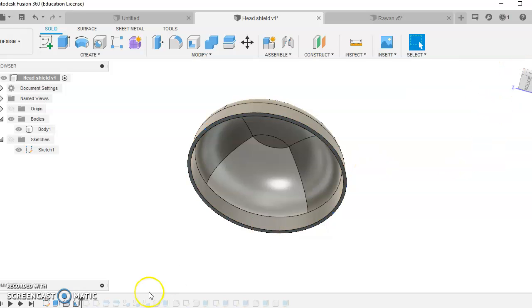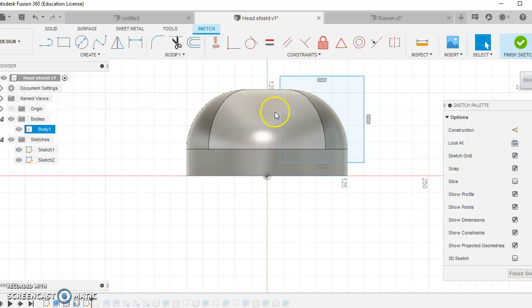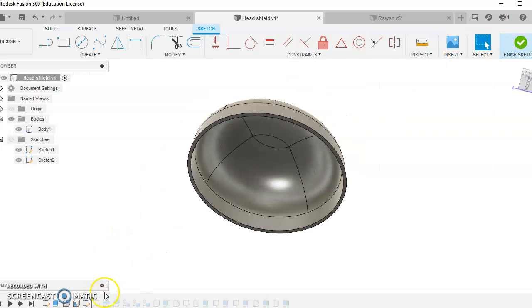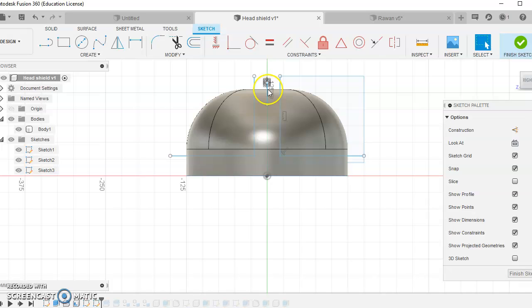Okay, so once you've got the shell done, you then go to the next stage. Now here, if I go to Edit Sketch, you can see I've created a rectangular shape. I've got a center line next to it. I mirror about that center line. Okay. You'll see on the next sketch here. Edit Sketch. By mirroring about a center line, it then means that I don't have to worry about the other side being an odd measurement.